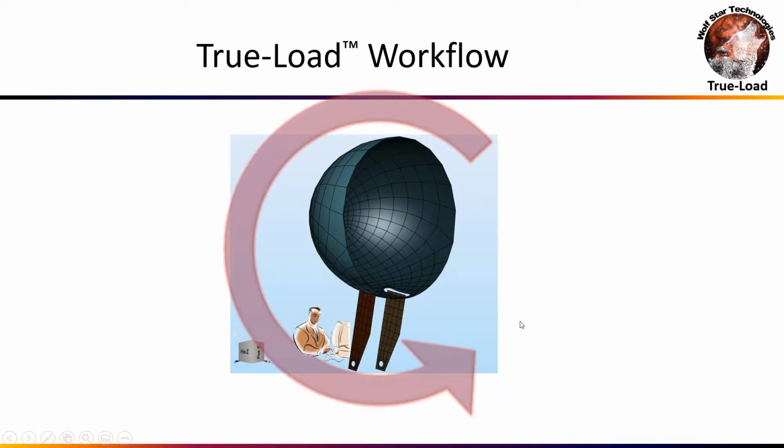Okay, I'm going to go through the workflow one more time with a little bit more graphics here. This will explain things a little bit better. This guy's working on a headlamp from a motorcycle. The analyst is saying the headlamp is attached to the handlebars, which is attached to the front, which is connected to the front suspension, which is getting input from the engine and frame vibrations. He's going to treat this as a base excitation problem. So he's going to restrain it to ground at the bolts and put 10 Gs X, 10 Gs Y, and 10 Gs Z. And he says that he can basically simulate any sort of base excitation with these three accelerations.